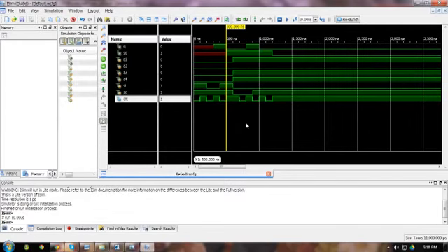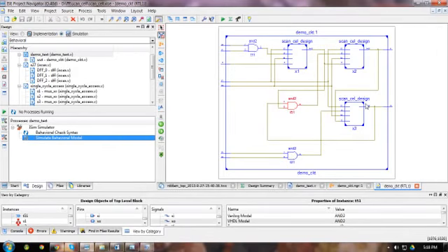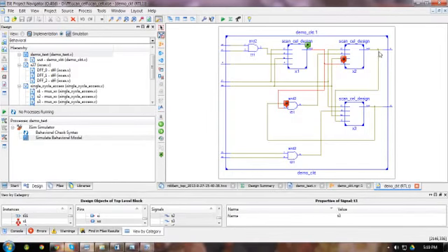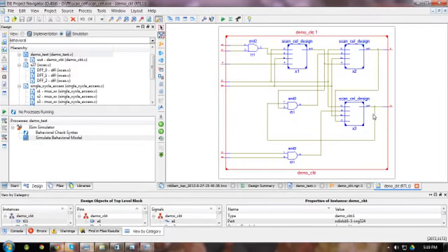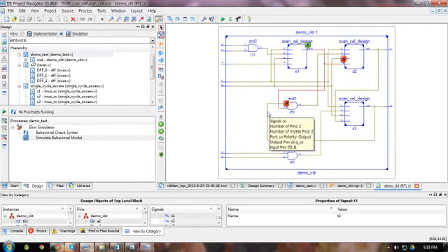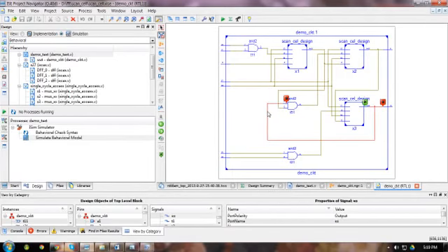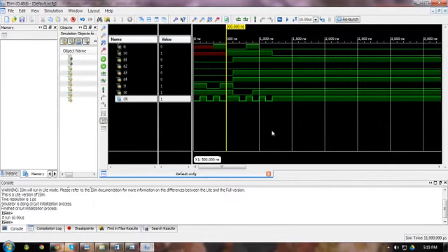It means after 3 clock cycles, I have actually given 101 to be present at the output of my scan cell 1, scan cell 2 and scan cell 3. Indirectly, I have set the first input of the AND gate to be 1 and the second input also to be 1. That is what I require. That's why I have shifted 1, 0 and 1, so that the first and the last, 1 and 1, get applied to my AND gate.